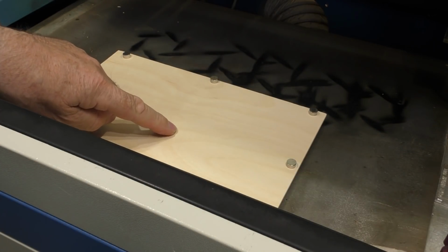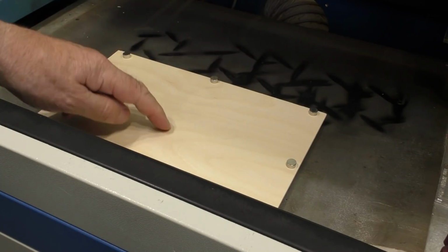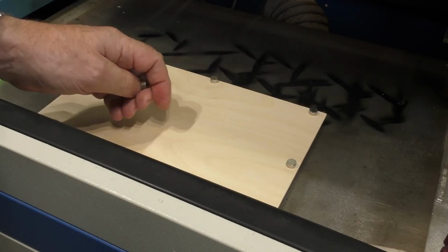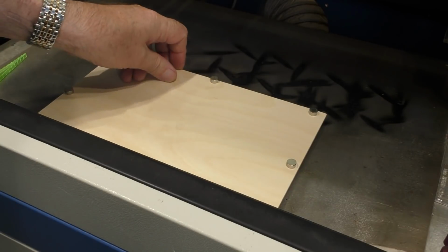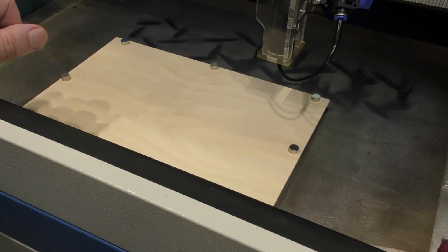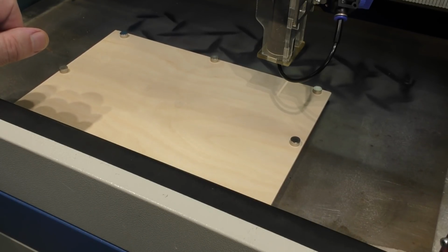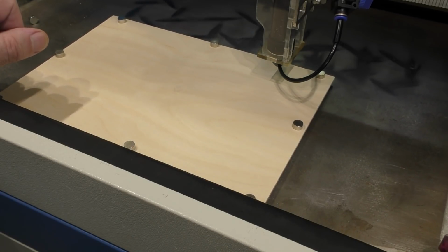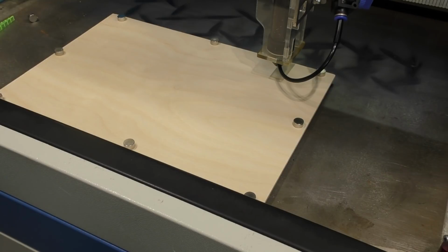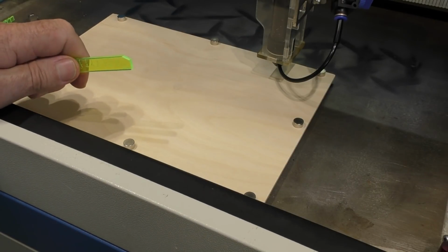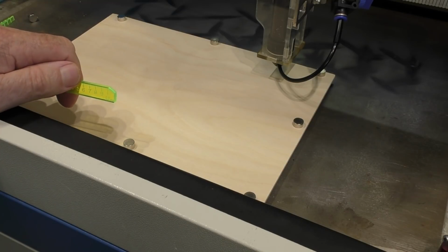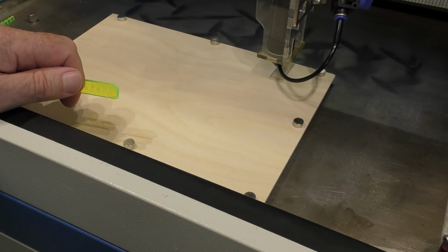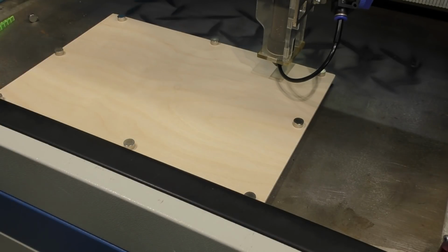It's okay in the middle there, it doesn't push down, so if anything, it's supported by the magnet underneath. If it was lifted up, I would put a magnet in the middle there as well, but I don't need it. Now, as I've mentioned to you before, you cannot guarantee absolutely that the focus is going to be the same for every wood, every material, every speed and feed that you use. So I think the nominal speed that I used on here before was round about the same at 150mm, but I think I put the power up to about 20 or 22. So I'm going to do my little dot test at the same parameters.